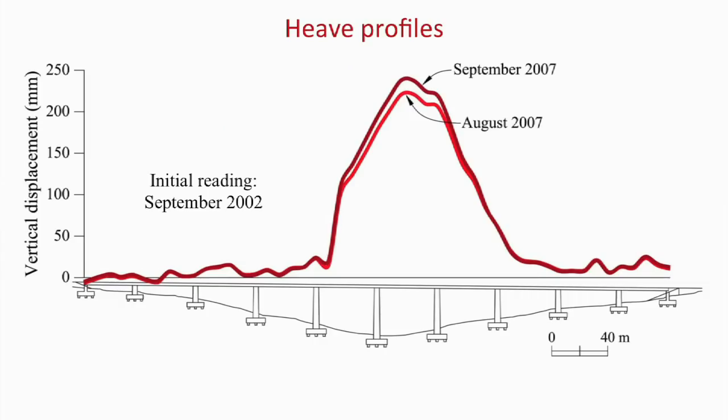Now, the railway administration realized, over the years, that something was wrong because those pillars were going up. And if you look at the scale here, in a number of years, 5 years or so, they went up, well, something like 250 millimeters, 25 centimeters. The trains here run at a speed of around 300 kilometers an hour. So, of course, they were correcting that almost every day.